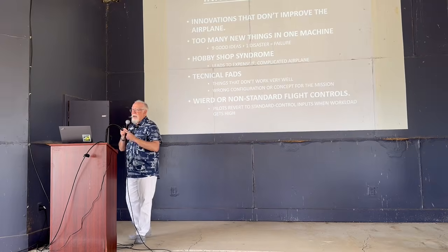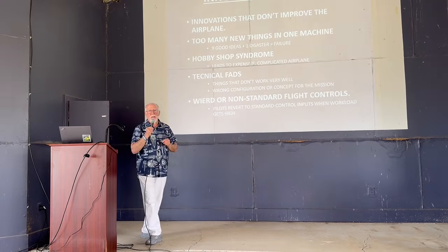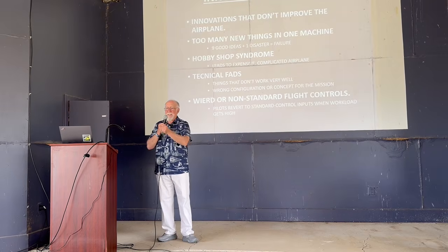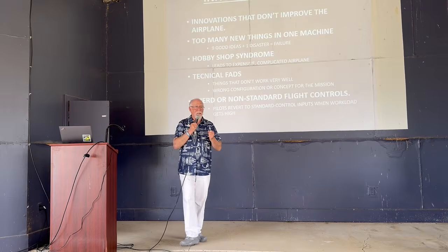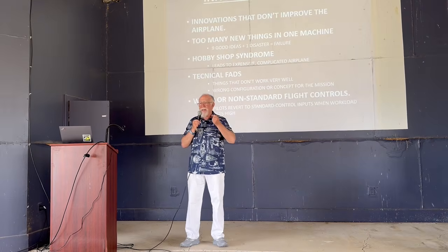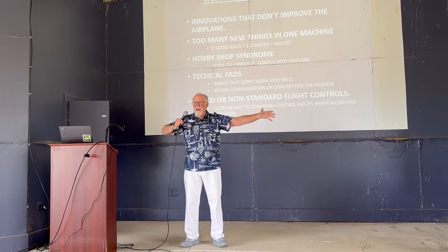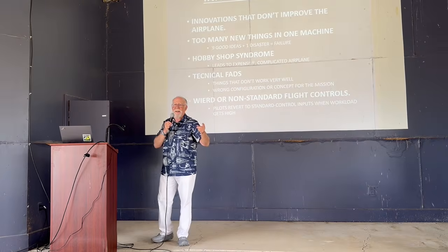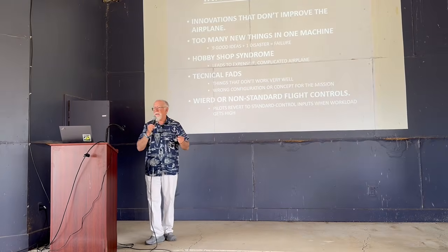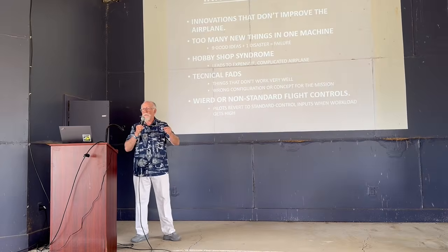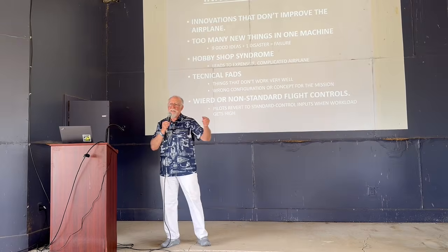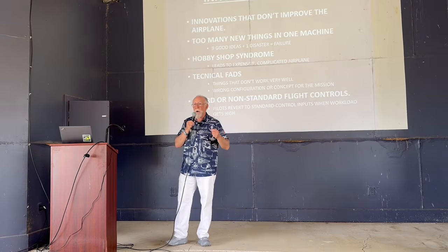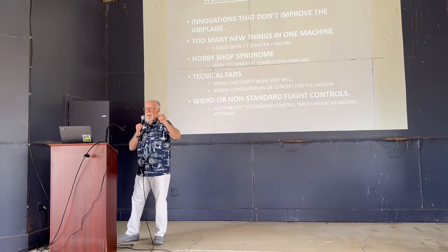Another one that is really important and catches people out is non-standard flight controls. Pilots are trained kinesthetically to operate the stick and throttle a certain way. People have tried things like overhead sticks or, let's fly like a bird controls, and what happens is the pilot reverts to muscle memory when the task load gets high and bad things happen. This is, by the way, one of the reasons why it's very difficult for someone who learns on a weight shift trike to transition to a conventional airplane or vice versa, because the sense of the controls is reversed. And they both work if you train them properly, but switching back and forth is hard.